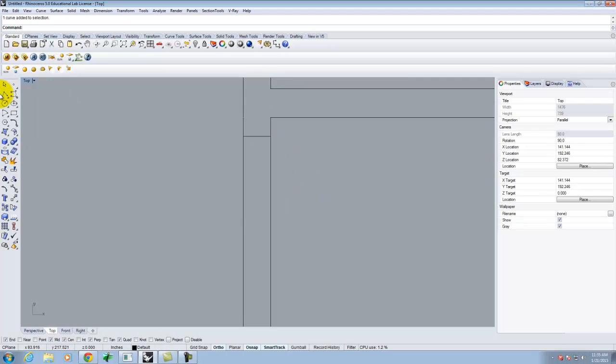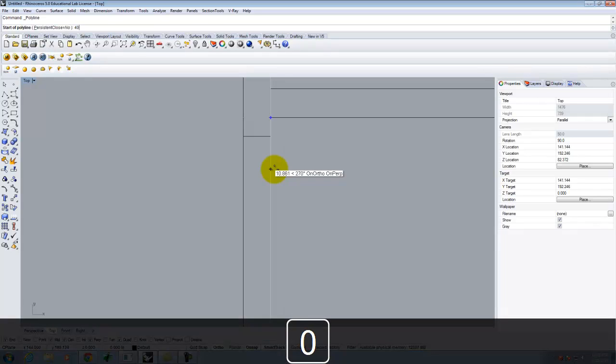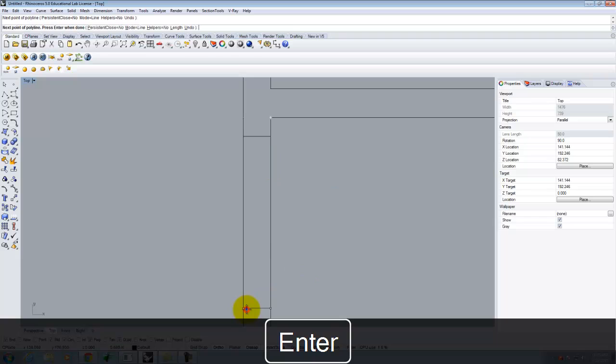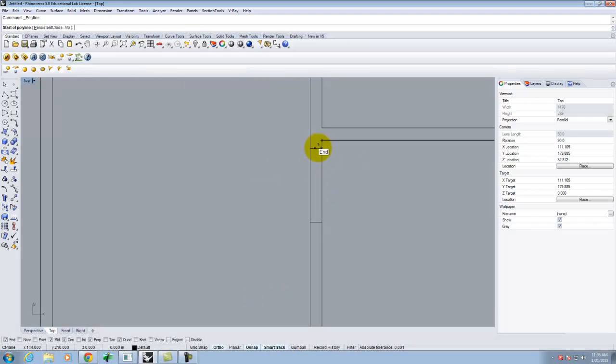Likewise, if I did a little mental math to reinforce this, I set my point and I drag out to get that white line. I would have the other end of the wall being 36 inches plus 4 inches, which would be 40 inches. And then I could specify 40 inches, and then I can draw that line across. So I didn't use the offset command, I used actual measurements to be able to do it. Just another way of doing it.